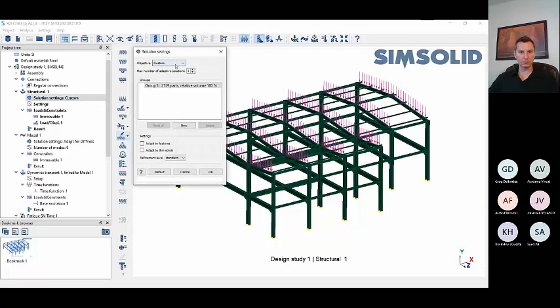Although in the structural setting, you have the adaptive solutions. As I've told you in the starting, as the solution progresses, it adapts to and adds degrees of freedom in various bodies within the model. So if there is some model problem over here, you can just increase or decrease the number of adaptive solutions over here.